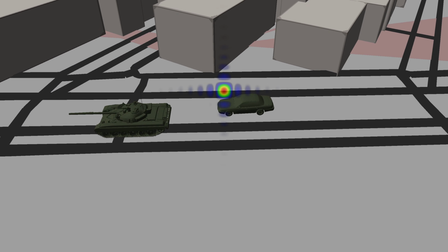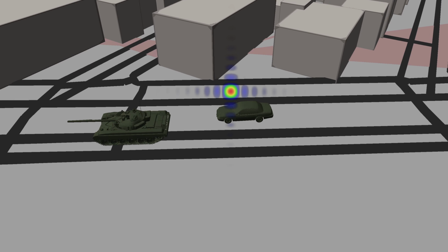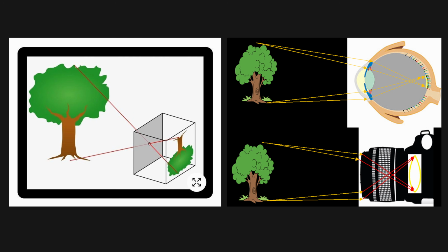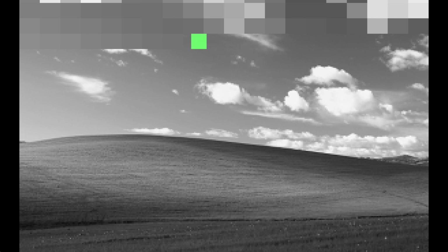You can't form good images with an ordinary radar because it only has one angular pixel with very low resolution. In a camera, there are millions of pixels on the focal plane, so it will record the light at thousands of angles in each direction from the boresight to form an image. A static radar can measure range, but it can only image one angular pixel at a time, so it would have to drag the radar beam across the entire scene to form an image.